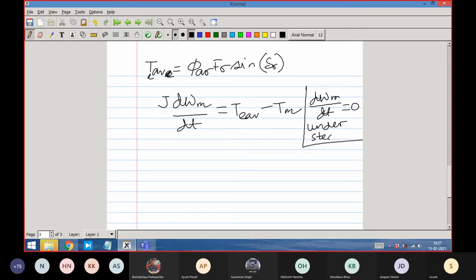This is the basics of mechanical engineering. As I said, machine is an interaction between electrical and mechanical. Just electrical cannot decide everything. Mechanical has to be given its role, and the mechanical role is damping. It is putting a kind of counteracting torque on the rotor. That is a mechanical load's property. It could be fan type of load, pump type of load, and they have different characteristics. When I say mechanical load characteristics, what do I mean by this? It also has a torque versus speed characteristic.